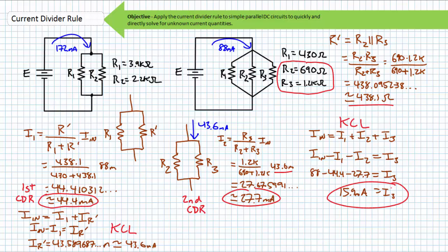You'll see when we step into series parallel analysis, I routinely employ the VDR again and again to quickly and directly solve for required voltages and only apply the CDR if backed into a corner. This being said, when backed into a corner, the CDR is a quick way to get out and continue cutting your circuit down to size.